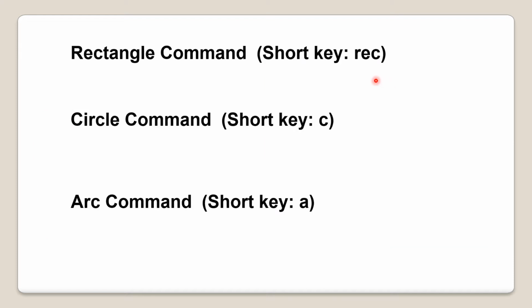The next commands are rectangle, which I will also show in detail, and the circle and arc commands. The shortcut keys for these commands are REC for rectangle, C for the circle command, and A for the arc command. Now let's try these commands in AutoCAD.